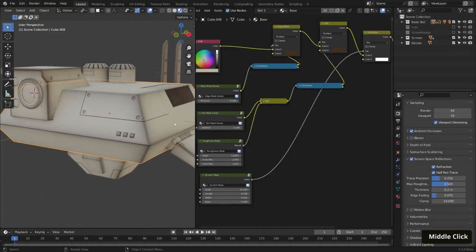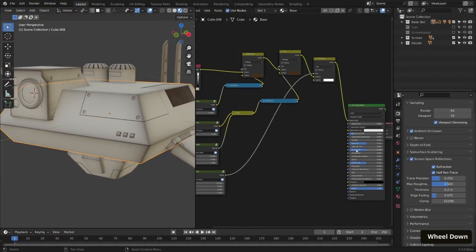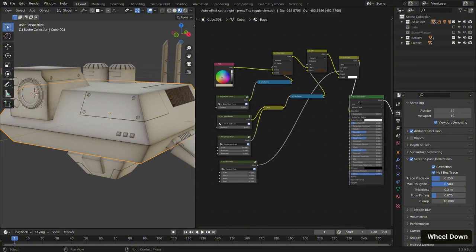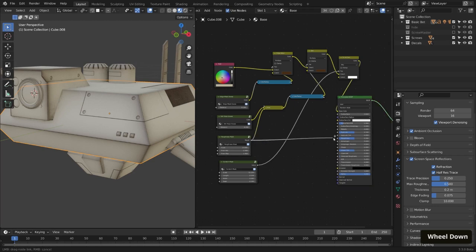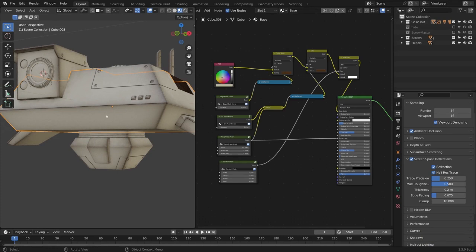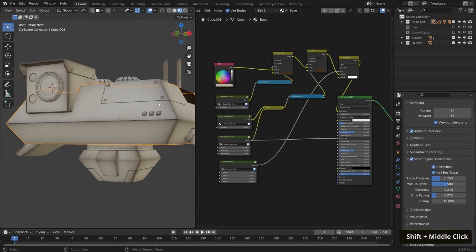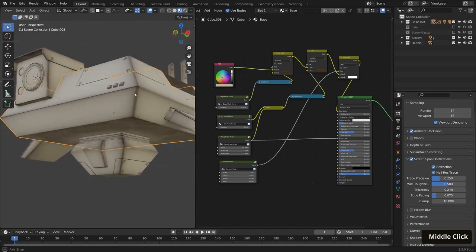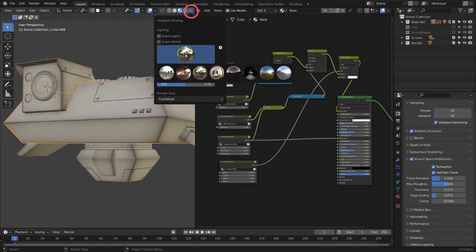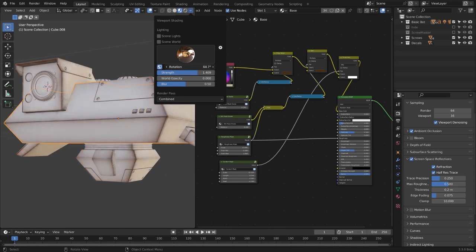Okay, everything is still looking kind of uniform. So let's start adjusting the roughness. So we can take our roughness mask and pretty much plug it straight in to see what it starts to look like. And now is a good opportunity as well just to note all of the different HDRIs we have to work with, because some will be better at accentuating the surface reflections. So let's just toggle the drop down here. And I'm going to select an HDRI with a little bit more light and dark variance. Boost the strength and rotate it around.